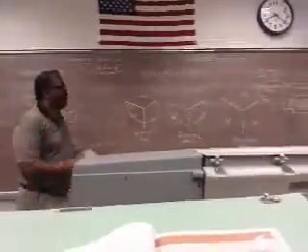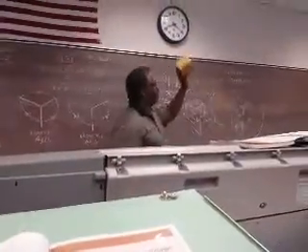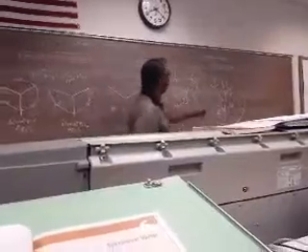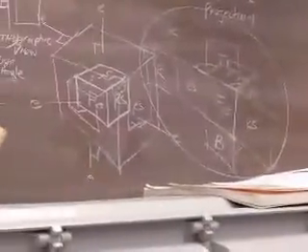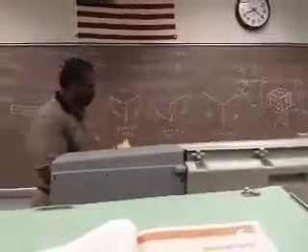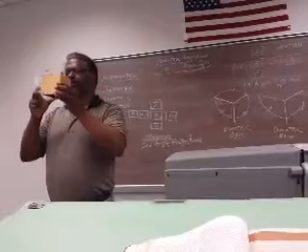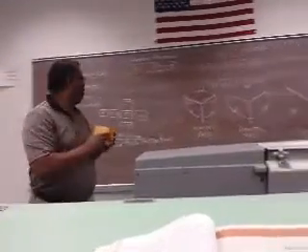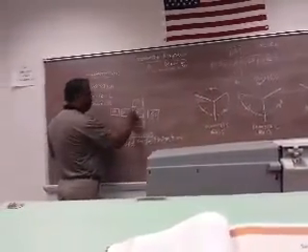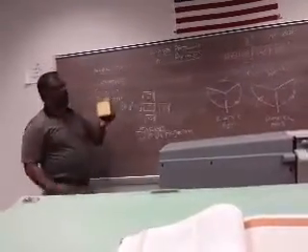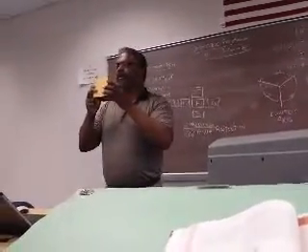In this example, we took a box and we drew an isometric of it. An isometric drawing simulates an isometric projection. If you look at the initial view here, it is parallel to your plane of projection, so if I just looked at this, this would be my front view. But three-dimensionally, we have an axis here.